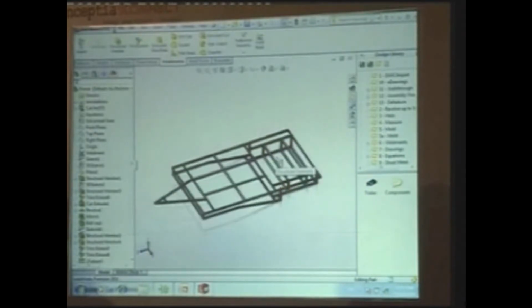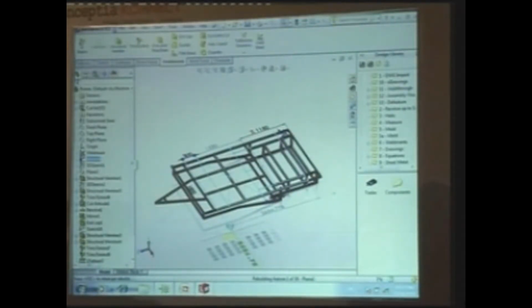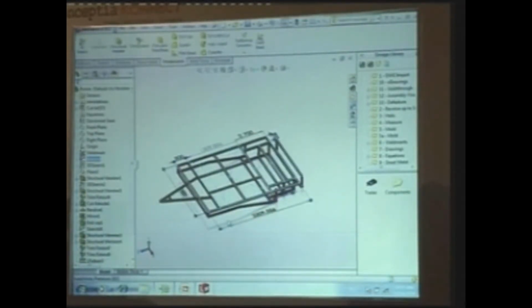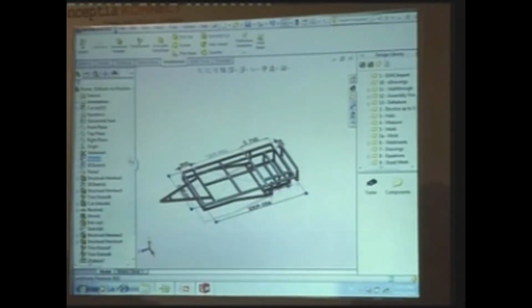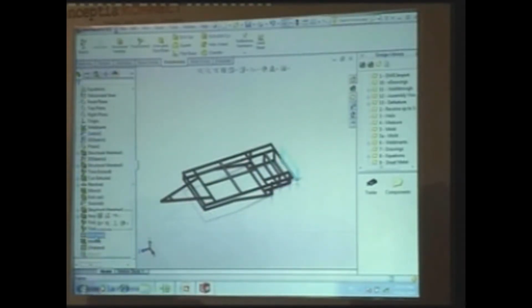So this is the frame which I've got, and based on the customer requirement, I'll just change the design here. Say the number of panels and the number of wheels required also depends on the load which I've applied here, right? Yes, that's so. Ashwin, have you made any changes here? Yeah, one of the weldment groups is left out. Correct. And also you can see that one more pattern is not linearly spaced.